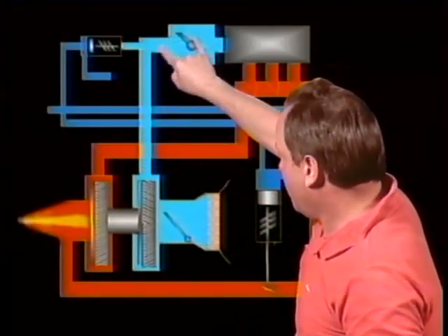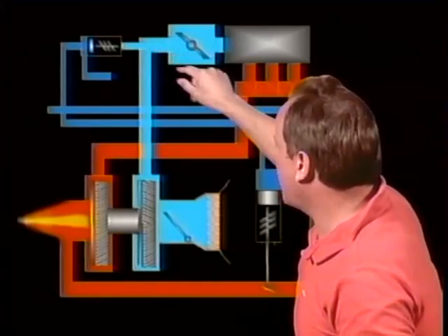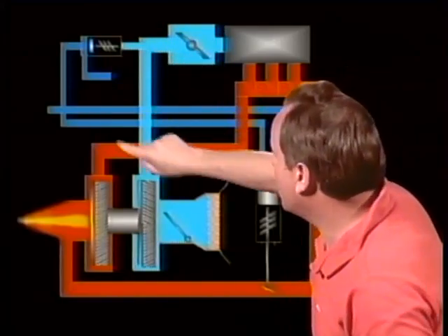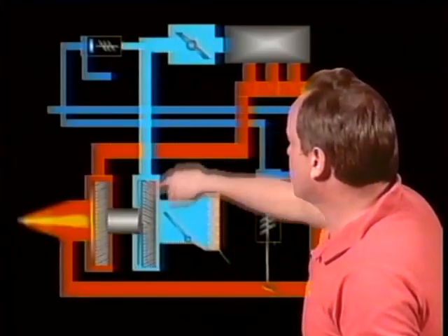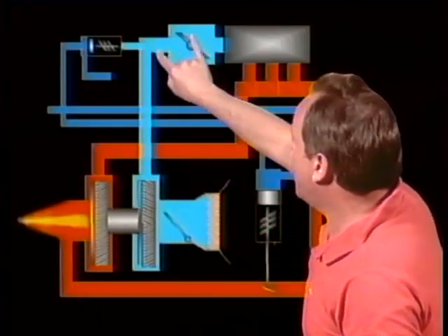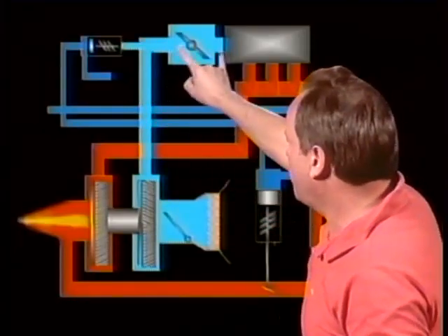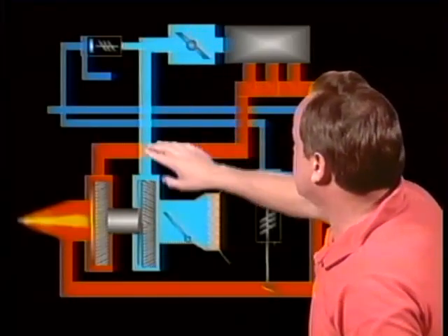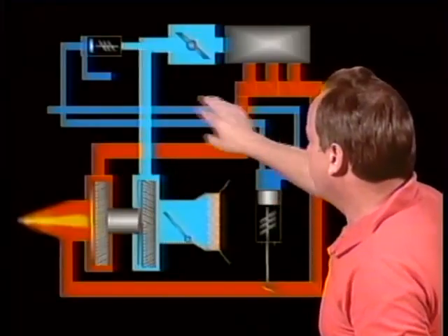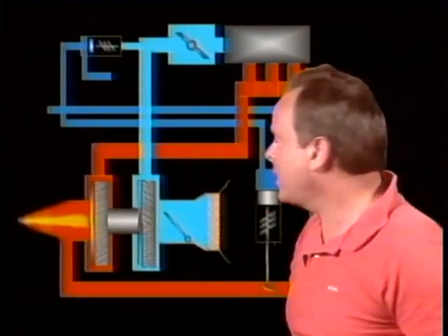So you have a differential controller, and when the difference gets to be too big, there's too big a manifold pressure drop, it bleeds oil pressure off of this actuator and opens the wastegate, so that the turbocharger doesn't work as hard. If there is not enough difference in the air pressure on either side, there should, we'll say, be a 2-inch air pressure difference on either side of the throttle valve. If it doesn't sense that, then it stops bleeding off the oil pressure from the wastegate actuator and closes the wastegate and speeds up the turbocharger, and that's the way that whole system works.